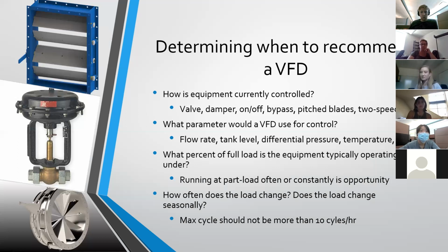If that's the case, probably not a good candidate for a VFD. If it's designed to run at 500 GPM, or gallons per minute, and it's running at 250 three days a week, 300 one day, 400 the next, and then 500 one day a week, then that might be a better candidate because you're at 50% of your design rate.